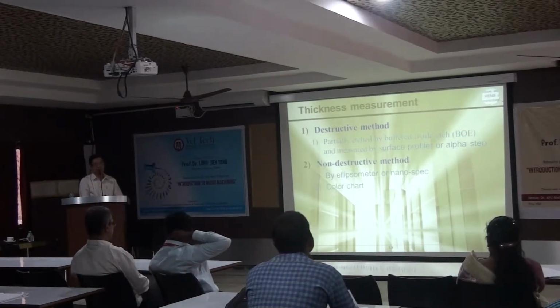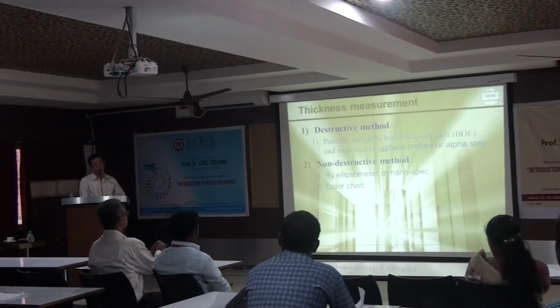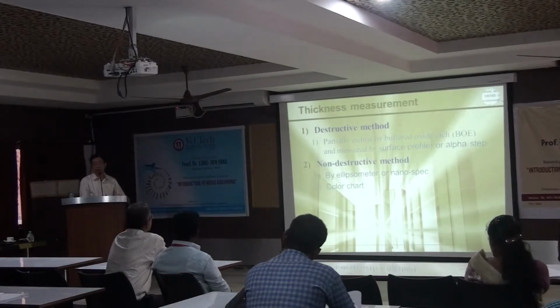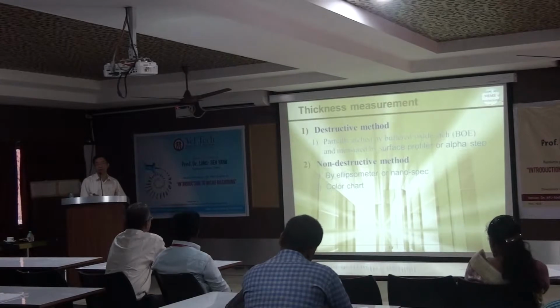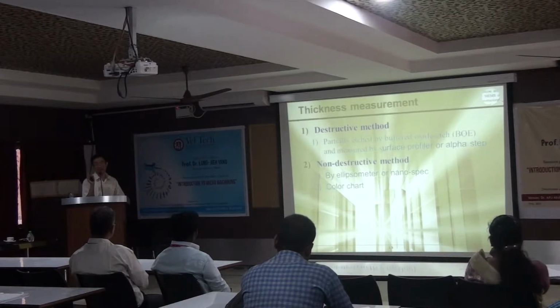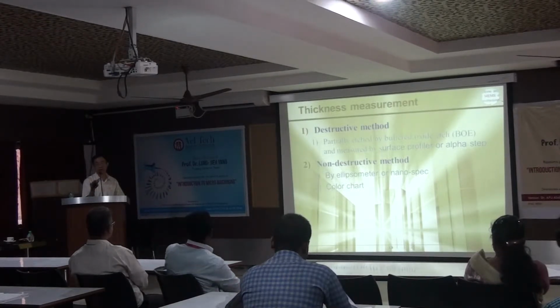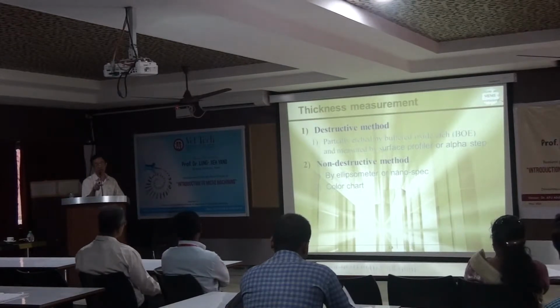BOE is dilute hydrofluoric acid. The only acid that can attack oxide or glass is HF solution, called hydrofluoric acid. It's a very dangerous one. It's similar to DI water, similar to water: transparent, no smell. But very dangerous. If you touch it with your hand, your hand will get permanent damage. So you should be very, very careful about the BOE.